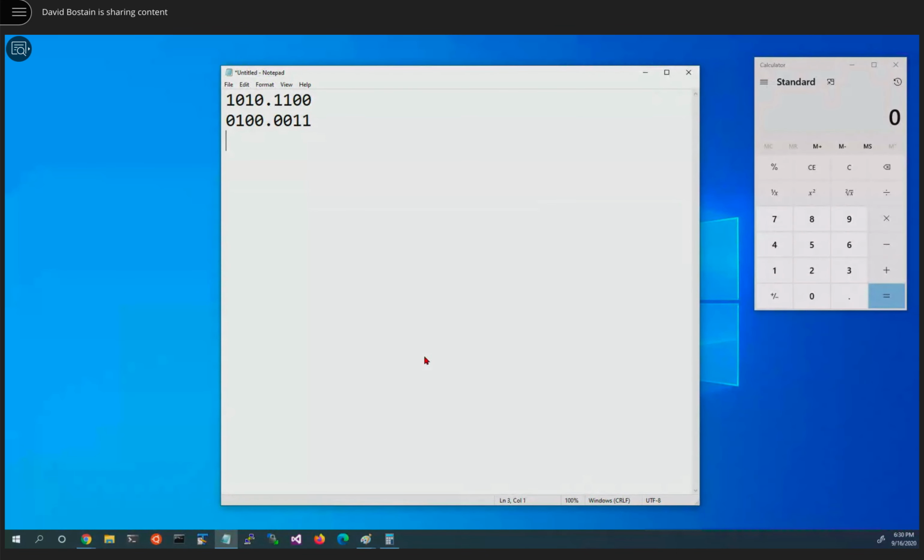So fixed point is rather easy, but it has very limited hardware support. Basically, we have to remember where this dot is because we're only going to be given this number and that number, and we're going to know that the decimal point stayed 4 positions over because that's the way adding and subtracting works. Now, if we multiply things together, that's not exactly the case. If I take 10 and I multiply it times 5, I'm going to get 50, right? Well, the 10 looked like that and the 5 looked like that, so our decimal points being lined up didn't really help us determine where things were in the final number.